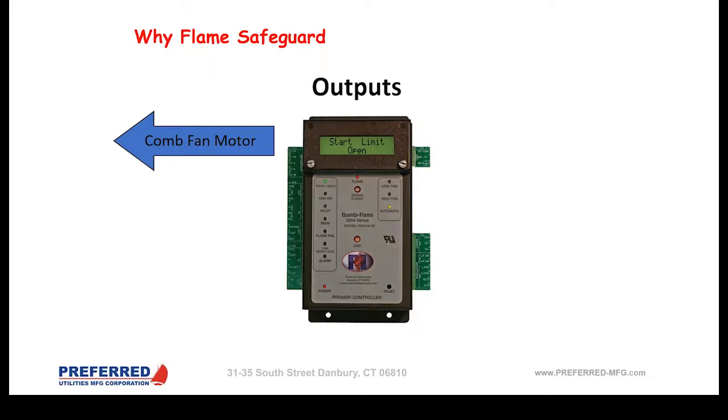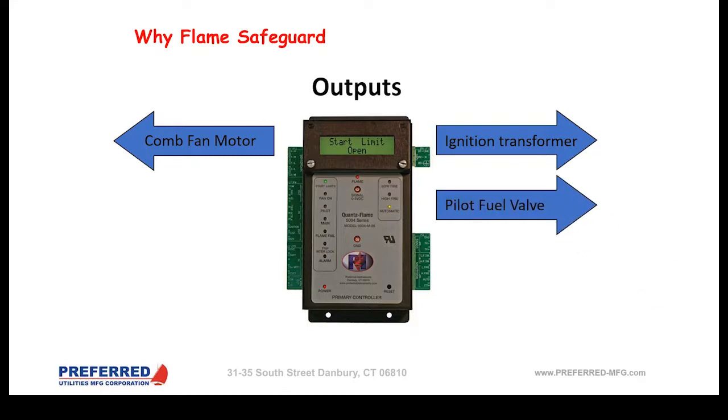And to your point also, the safety permissives are different also. If something is not in the proper position, say you had draft control and it's not open when you have an operating control, it's not going to continue the start process until obviously a safety permissive closes, and also could be airflow control also. Okay, thank you.